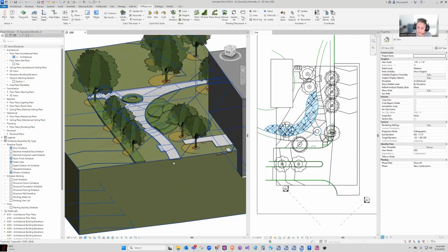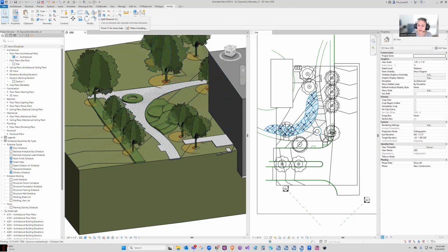And then the other thing is it only works in the cutting direction. So it's not a true building pad replacement. There's no fill option. It's similar to the fact that we have a split functionality, but we don't have a join functionality for our topo solids. We have an excavate functionality, but we don't have a fill functionality exactly. It would be useful to have that, so we'll see. So in summary, excavate was the main change that we saw in 2025 with our topo solids.